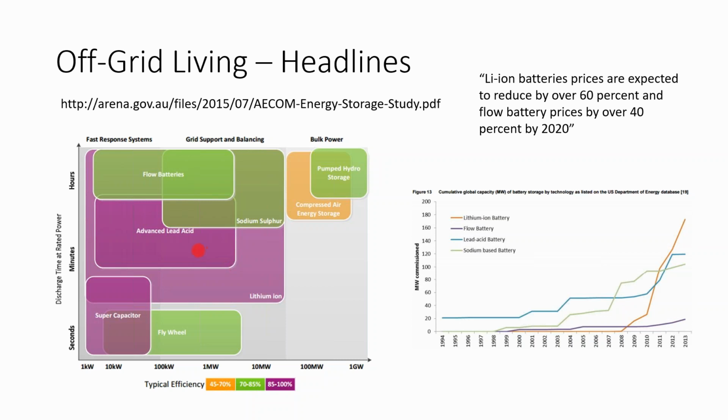So the fact that we lose a lot of our energy by discharging an industrial flooded lead acid battery for demand management, that might mean that it's not economic in California where energy costs are high, but it might make more sense in Colorado where energy costs are low. Under each system, you might get the same demand savings. And then it becomes, well, which technology is more cost effective, flooded lead acid or lithium ion? That really depends on the cost of the energy itself.